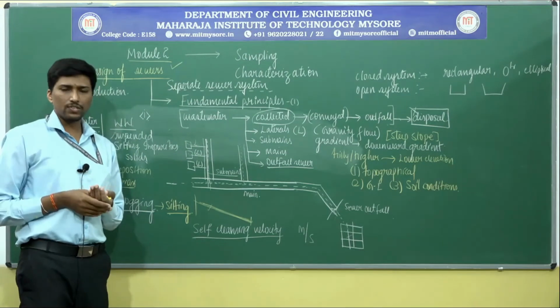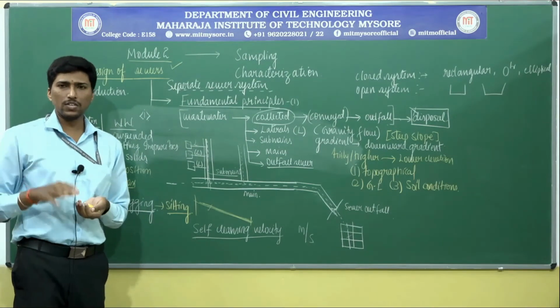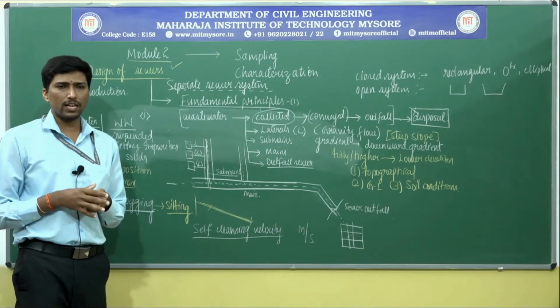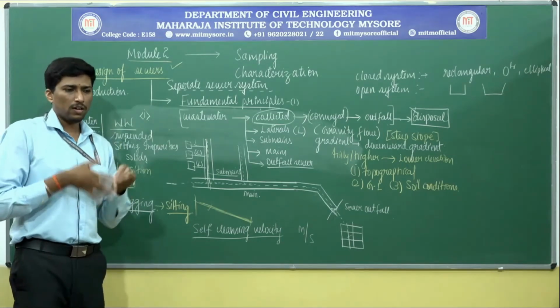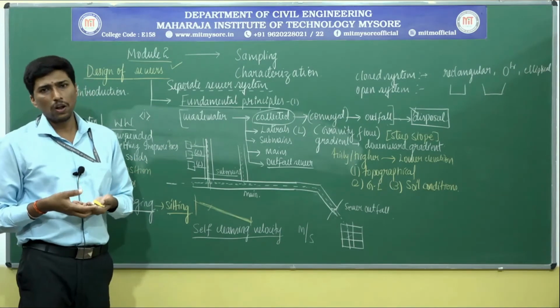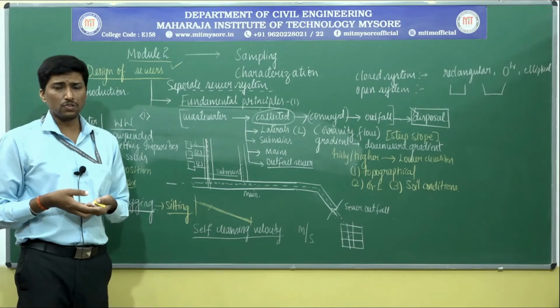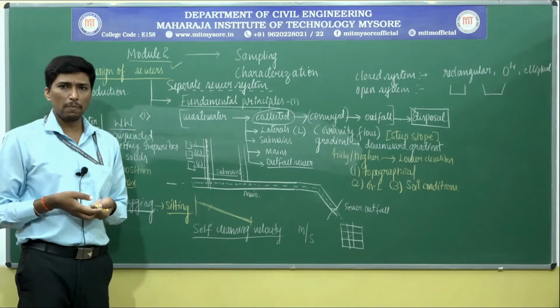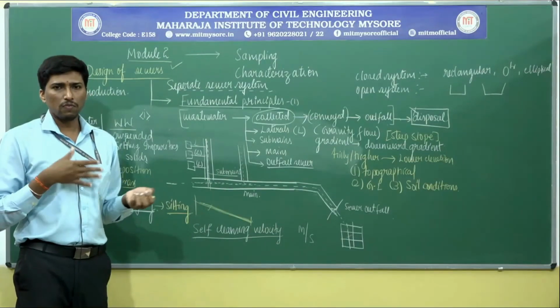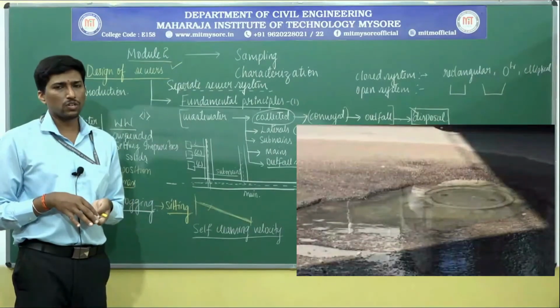We have certain things, laying and testing of the sewer lines, laying and testing of the pipelines. If any blockages are there, huge amounts of sewage containing a larger part of solid content or any debris or putrescible organic matter, they have to be removed right there. Otherwise, the flow is not uniform in nature.